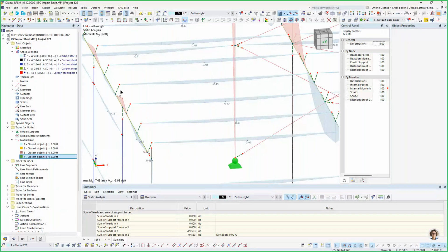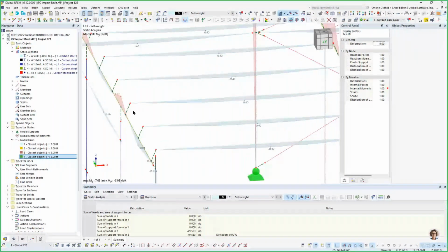The benefit of this is that for the steel joints add-on, you would have had to add these eccentricities in anyway. So if you wanted to add a joint in here for the coupling members to the beams, you would have had to add that in anyway.